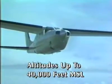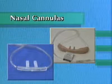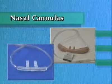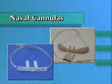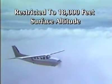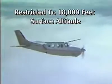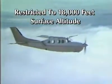With the proper flow rate, the phase sequential mask will supply adequate oxygen for a short duration emergency at altitudes up to 40,000 feet mean sea level. Nasal cannulas are also continuous flow devices and offer the advantage of being more comfortable. They are restricted by federal aviation regulations to 18,000 feet surface altitude because blood oxygen saturation levels can decrease if one breathes through the mouth or talks too much during flight.